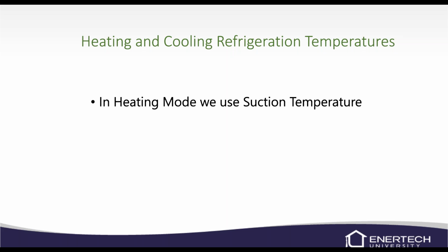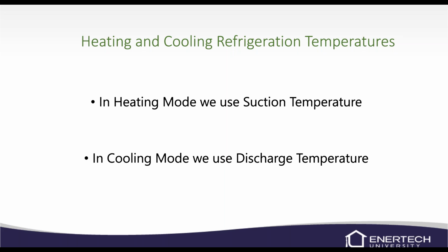So again, in heating mode, we're going to use suction temperature, so suction pressure converted to temperature. And in cooling mode, we're going to take our discharge pressure and convert that to temperature and just do the math. It's a pretty easy calculation, but it's just one of those things that you don't use every day. And so you might forget about it, but it's always a good little service tool to keep in the back of your mind.